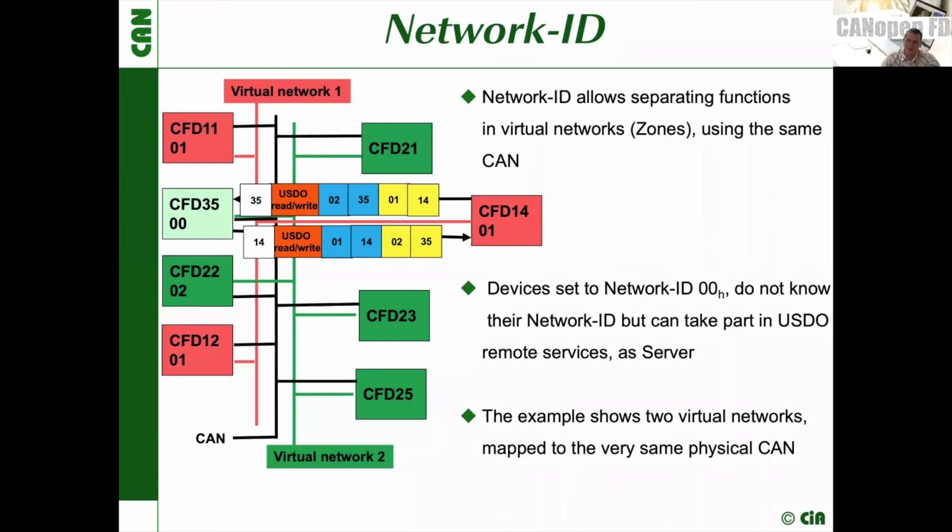All the devices that are located in the very same area are collected with one cable, independent of whether they belong to the very same application or not, so that you have the data. Then, on a virtual basis, you have to differentiate which devices belong to which application, how to deal with them and how to control them. Something like that we can already do with CANopen FD.